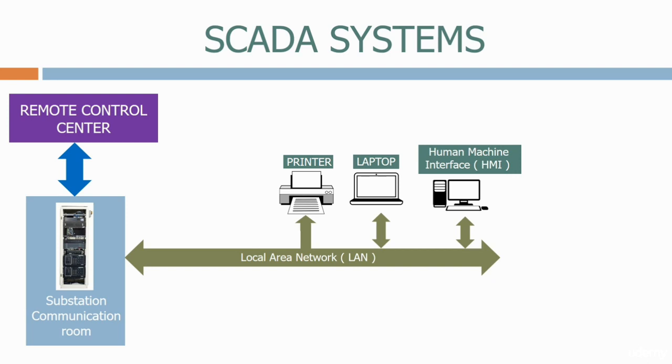It's really important for the SCADA system that all the events and alarms are time-stamped so that we know exactly when they happened. To do this, we normally have a GPS time-synced switch, to which all the protection and control equipment is synchronized.